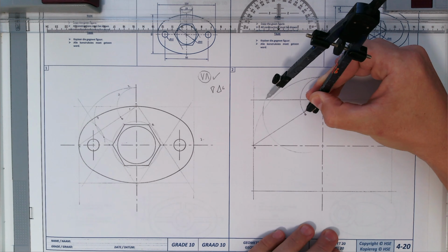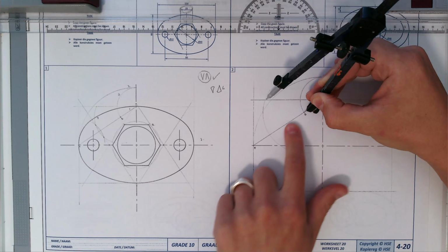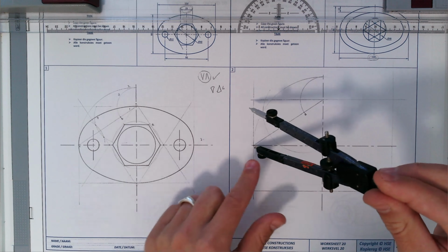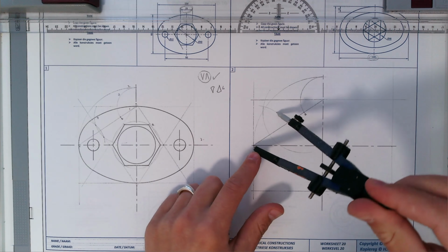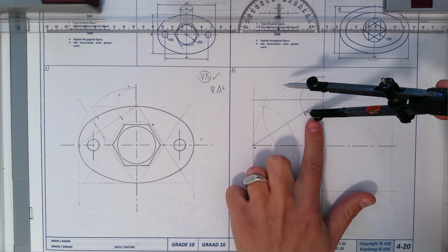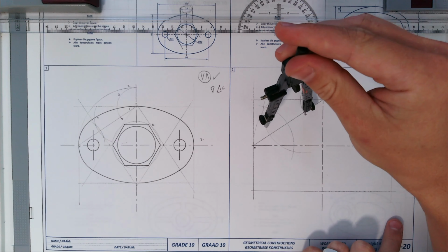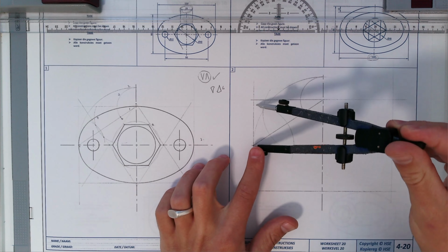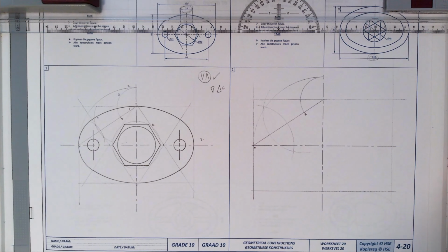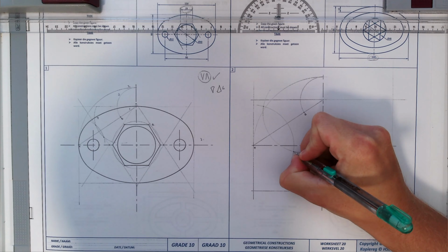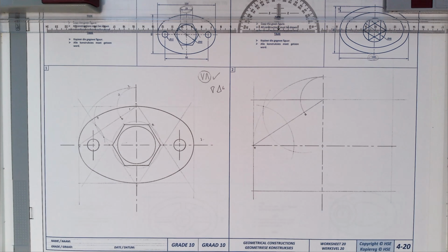Lighting construction. Then I'm going to take this point and we're going to put it at A. I'm going to repeat this process. I have not changed the dimension on my compass. Whatever you put here, you need to do it the same on this side. Now it's clear to you and to me that those two arcs meet over there and they meet over there.